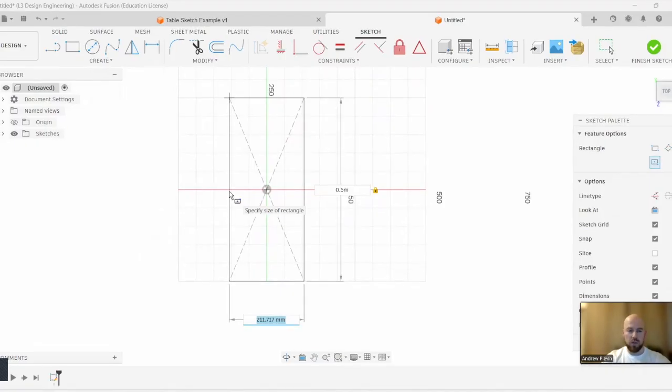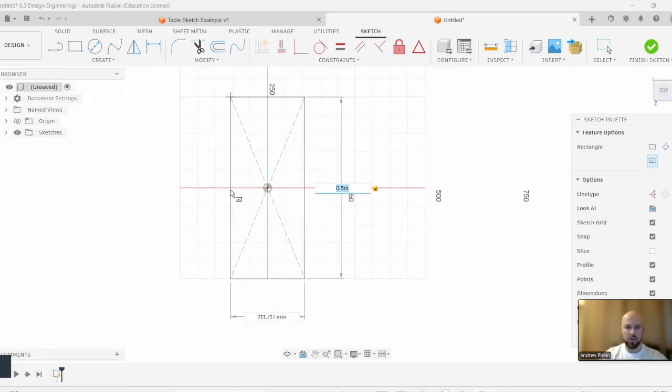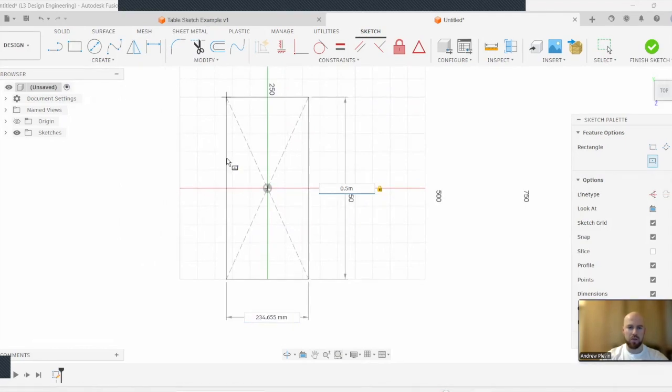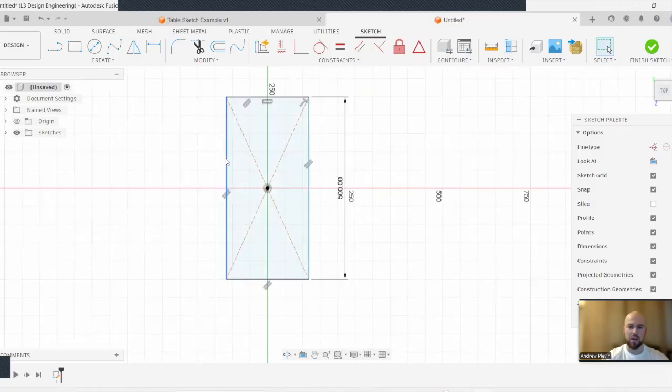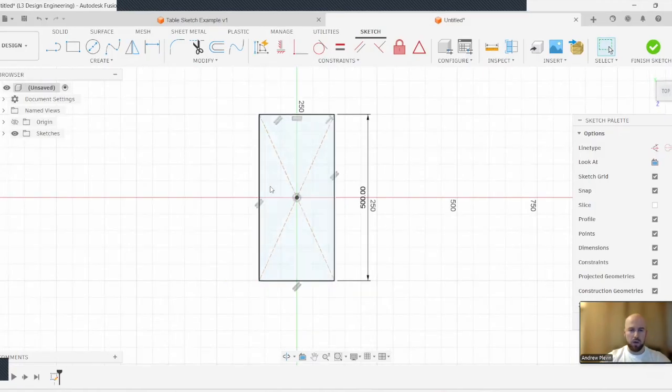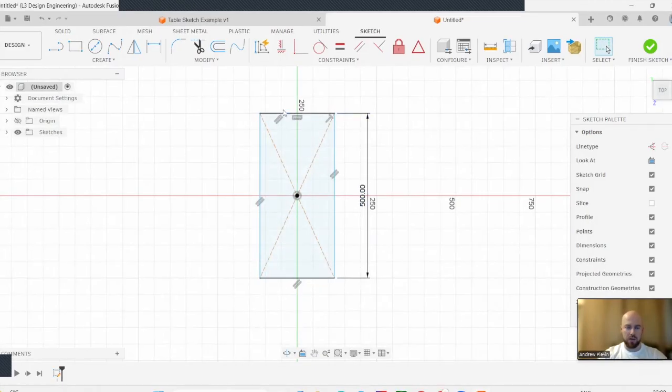To change over to the other side when using different shapes, you can just press tab on the keyboard. And the other side doesn't really matter for now, so I'm simply going to press enter. Then what we will notice is it will add that rectangle like so, along with that dimension just there to the side. We're now going to set out the dimension of this other size, but we're going to do it in a slightly clever way.